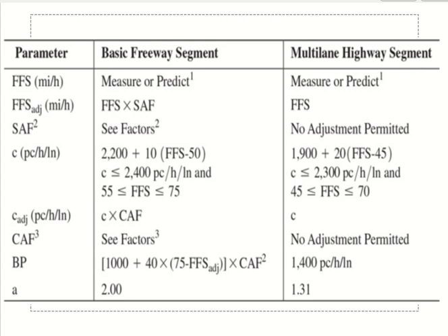This is the equation. I need to calculate density. Density is flow upon speed. I have flow rate. At this flow rate, do we have free flow condition? If yes, I can use free flow speed here. If no, I have to get some other speed. So now I'm checking, am I in free flow or not?